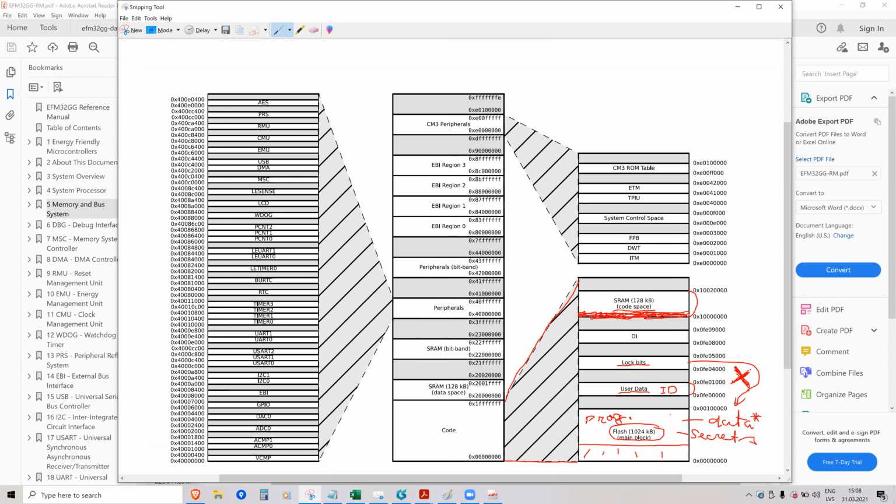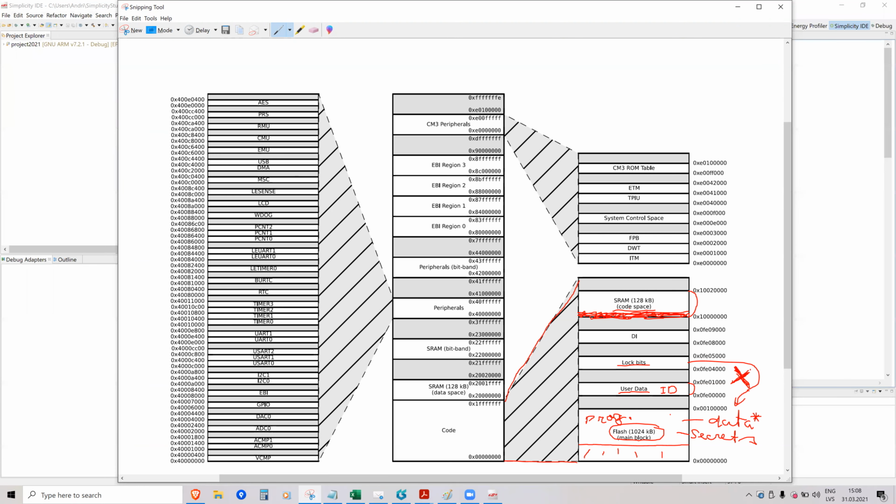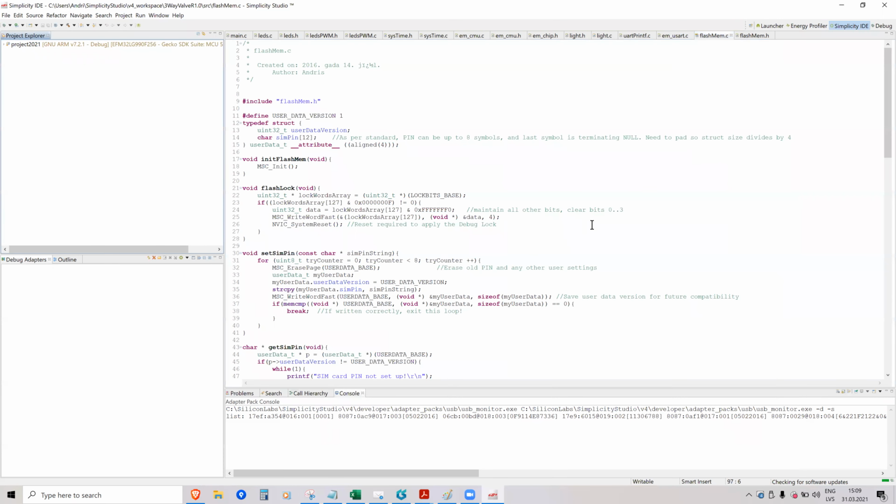It will consume some random access memory space, so you will lose some space for variables, but that's something you just take into account, and that's all. So you wouldn't want all of the program to run from random access memory. That wouldn't be as good. But the bootloader or program that rewrites the flash, you would want to tell the compiler to put in random access memory. And it's actually easy to do.